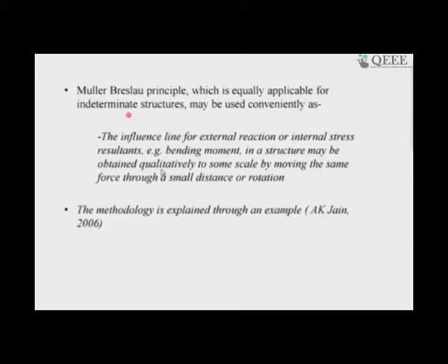If we apply this to a statically indeterminate structure, let us start with an indeterminacy of 1 for explanation. For an indeterminacy of 2, you need to remove 2 redundant forces and apply them back to see the displacements of the structure. Let us now examine a single redundant force and clear our mind on how it is applicable to statically indeterminate